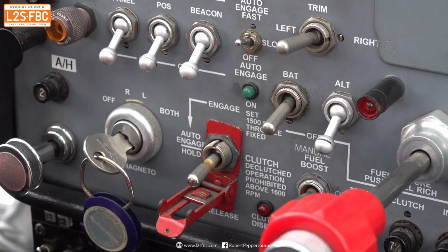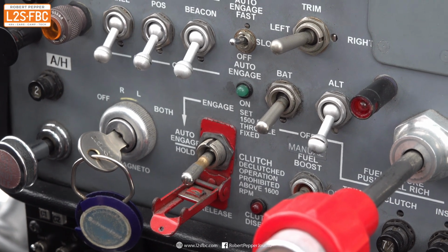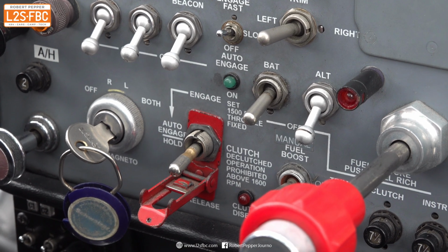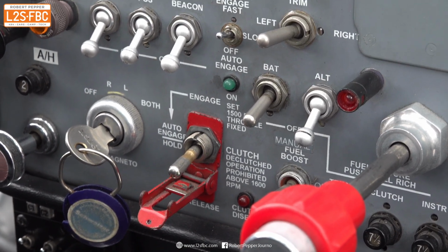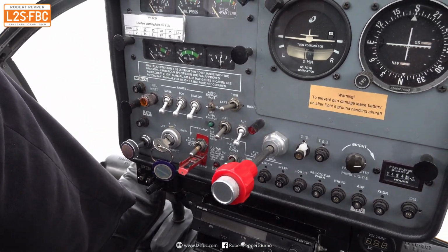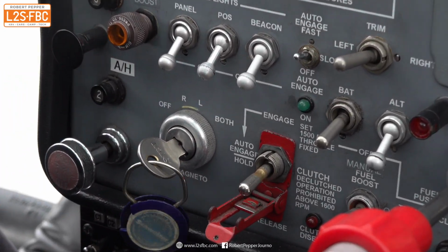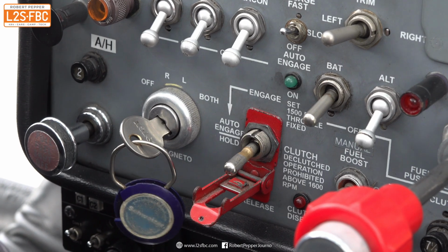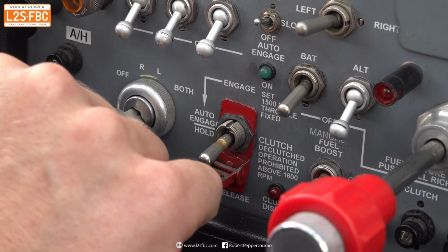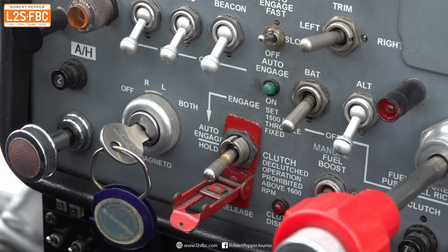What's a magneto? The magneto is a device that's attached to the engine. It runs synchronized with the engine, and it creates a high voltage spark in the combustion chamber. As a result, fuel and air that get compressed at the right timing are ignited. The magneto delivers a spark, and then boom, it sets the whole lot on fire, and we have our combustion. So in normal flight we use both systems, for redundancy, a right and a left to bring us home.